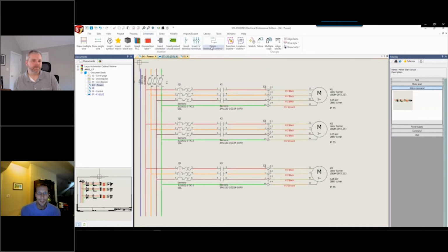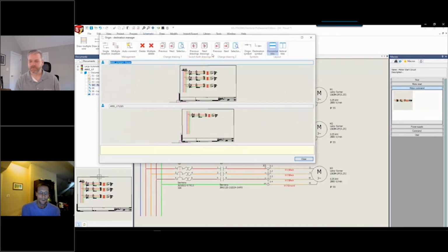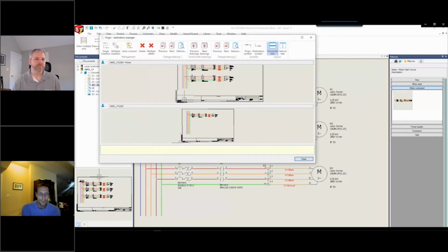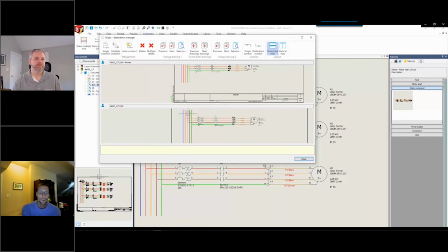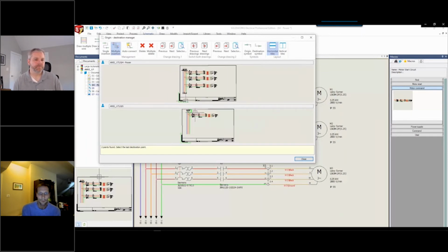So one last step to that is simply to tell the project where the circuit continuation is, if you will. So for that, we're going to use a multiple insertion from-to arrow, where I just simply go through, select my lines or line, and then it will find that corresponding connection. As long as there's continuity between those wire types, it will find that, and it creates that hyperlink.